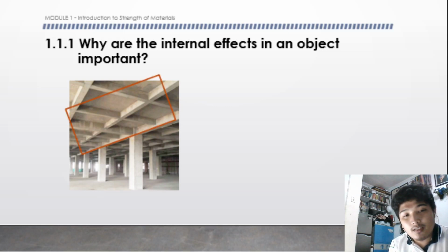So, highlight natin. So, let's say ang portion na yan is being carried by column. So, ibig sabihin, since weight yan, therefore, yung loadings niyan is directed downward. Okay? So, yung downward force na yan, dapat ma-resist yan ng mga column natin. So, para ma-resist yan downward force, edi dapat mag-react naman upward yung mga column. Okay. So, magre-react siyang upward. So, nakikita naman natin dito is that downward and then upward. So, ibig sabihin that a portion or the internal effect netong force system na to doon sa column natin is compression. Kino-compress niya yung column.